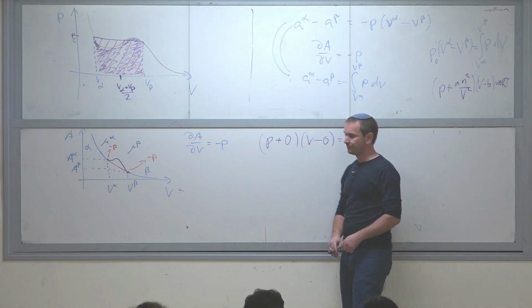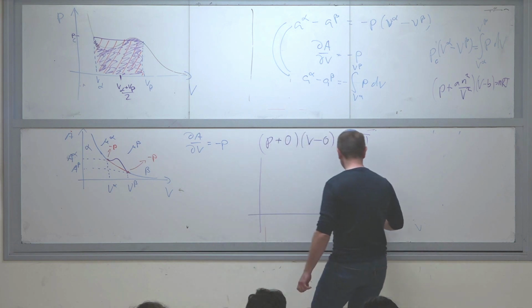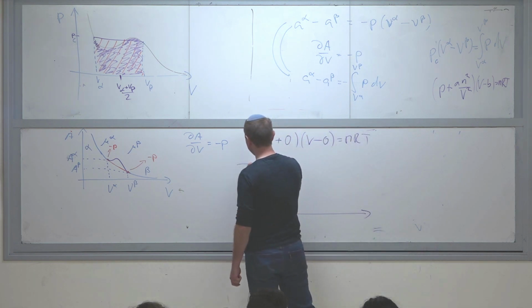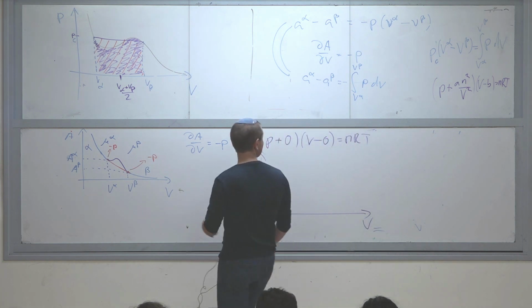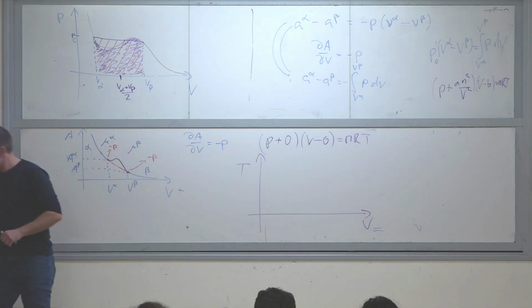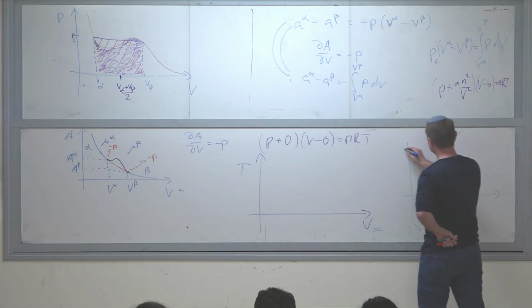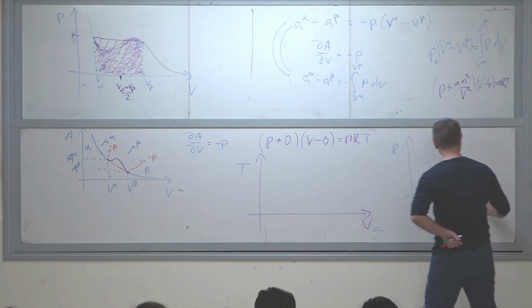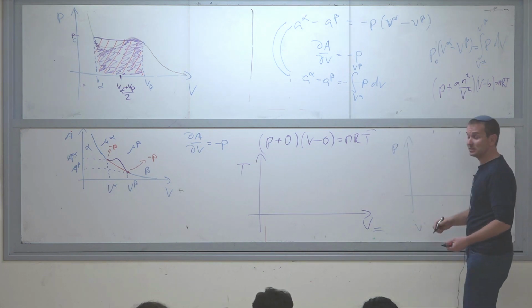Okay? You cannot describe the material with a volume that looks like this in between. The equation will try to say, yes, there exists a state that looks like this, but it's simply wrong. Okay. Maybe another way to describe it is if we plot, for each temperature, P against V, an isotherm.